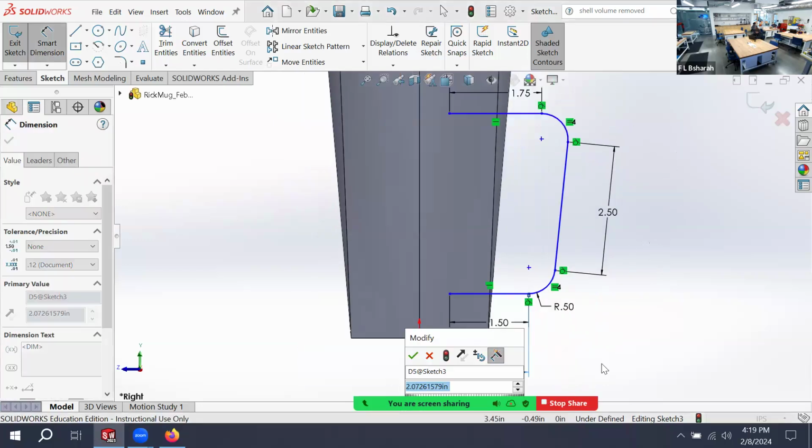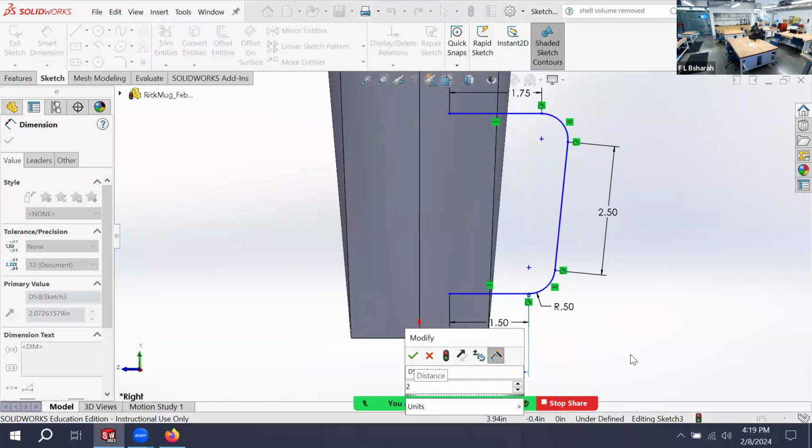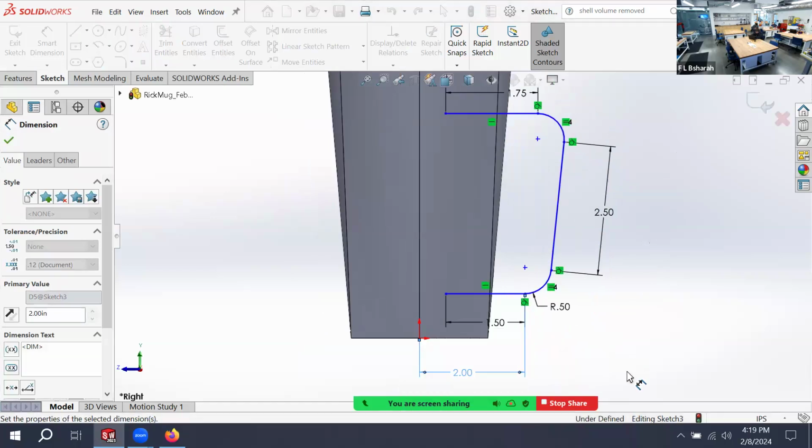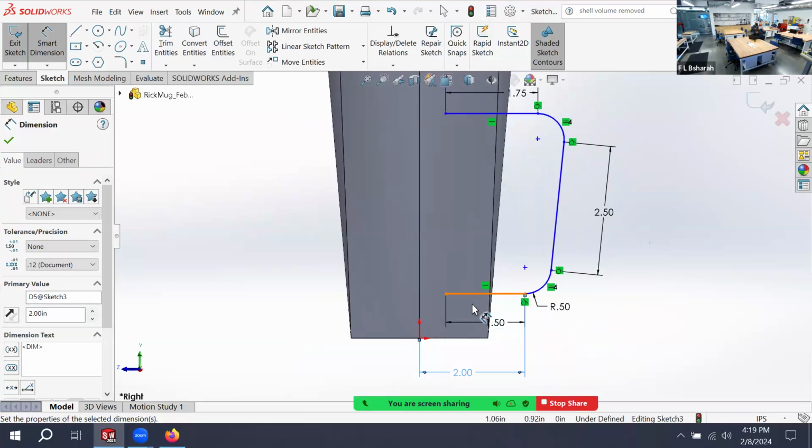And the reason I'm doing that, and I'm going to make this just rounded off to 2 inches, is I know later on I'm going to remove parts of this sketch because I'm going to chop away that material. And if I come back and edit it, I don't want it to give me any dangling or missing elements. So I'm just using as my reference point where this arc intersects this line versus this just arbitrary length of 1.5 of the straight line.